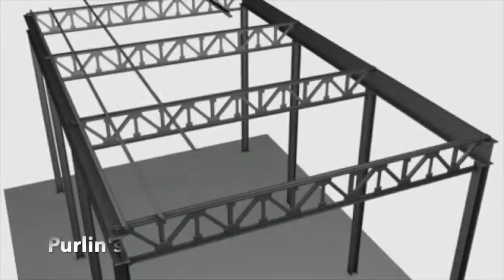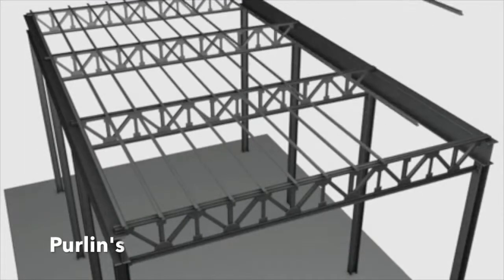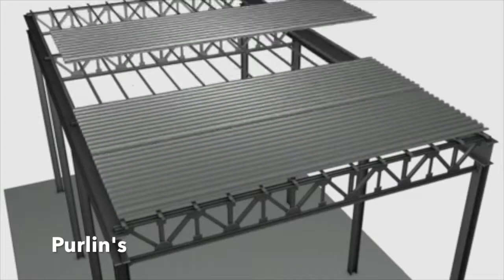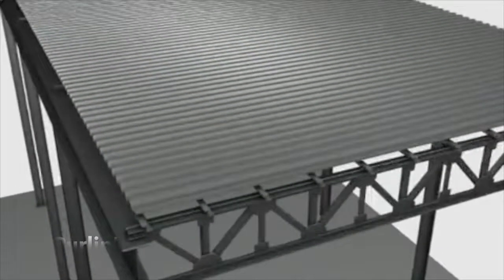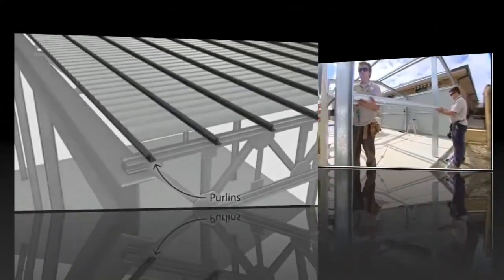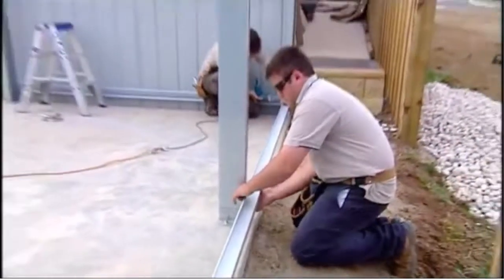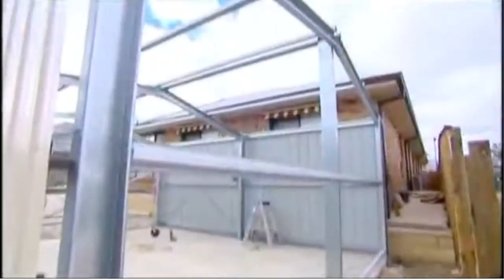A purlin is a horizontal beam along the length of a roof made from steel or timber. They support the common rafters and are also used to attach the roof sheeting. A girt is a horizontal structure member fixed to the frame wall. Girts provide lateral support to the wall panels, primarily to resist wind loads. They both play an important part in weight distribution for the shed design and thus were designed first.